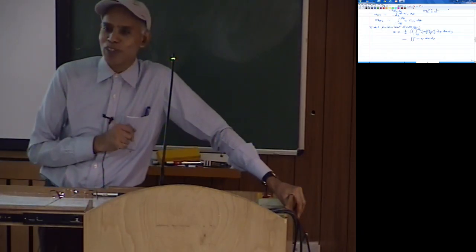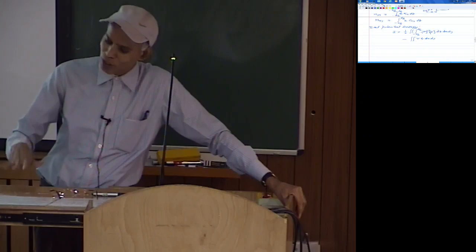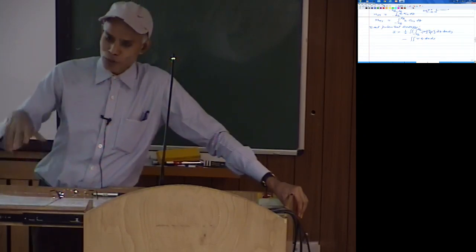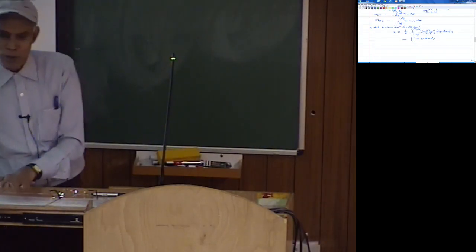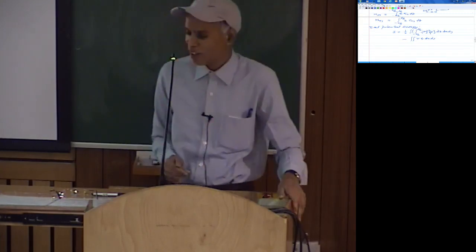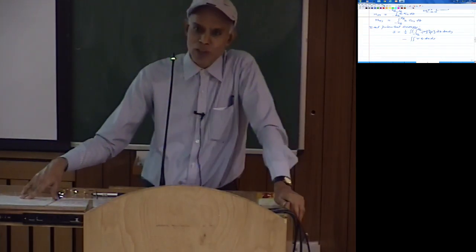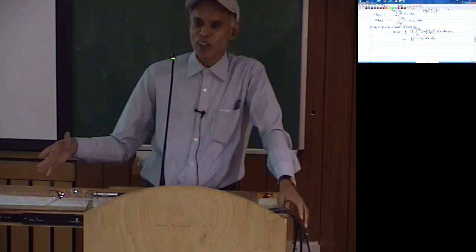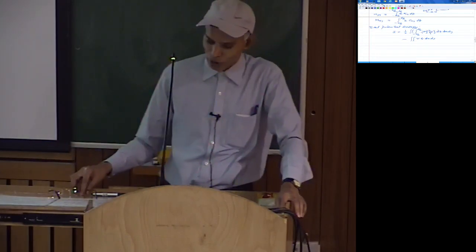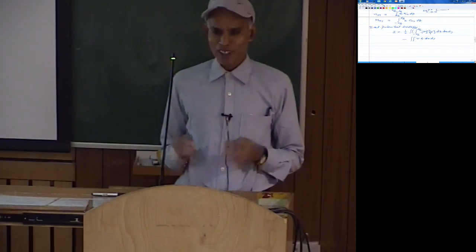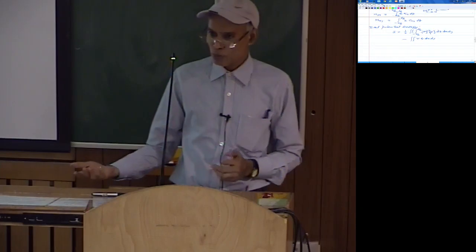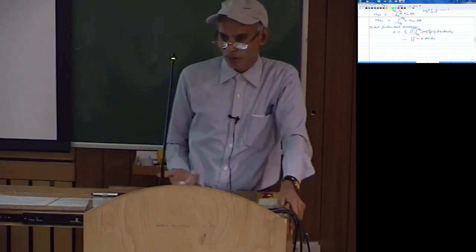So this Q that we are taking, even if there are different loads on the top and bottom, is actually the difference of those two. Of course, because you have a load from the top and a load from the bottom, there would actually be a non-zero sigma zz, equal to the intensity of the load here, but the dominant components of stress, sigma xx, sigma yy and tau xy, would actually be 0. So when you do plate modeling, it is essentially the difference of the transverse loads if they are acting on the top and bottom faces separately.